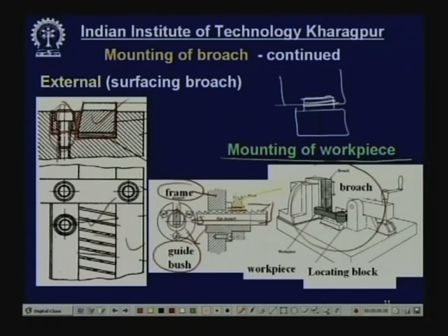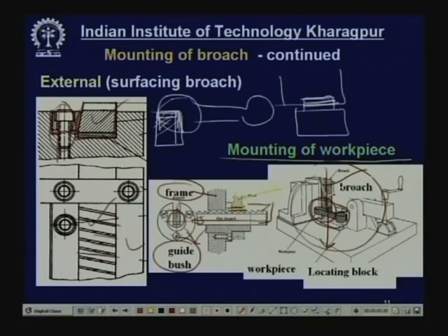Okay. So, this is the workpiece. This workpiece is like this. Now, you have to cut a slot like this here; this portion has to be removed, and this can be done by a broach. This is the broach which will move downward and produce the required cut, and the blank is mounted in this machine by this fixture.